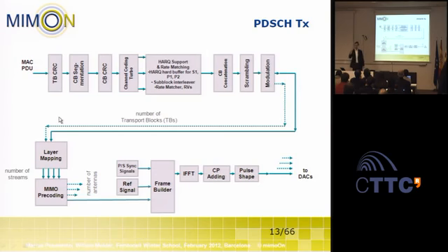So these up to two transport blocks can now enter the layer mapper, and in the layer mapper we adjust the number of streams that we have for MIMO transmission. If we have, let's say, a 4x4 MIMO system, we can use up to 4 streams that we simultaneously transmit from our antennas. This is achieved here in the layer mapper, where these 2 code blocks are further multiplexed into 4 streams. The streams in LTE are called layers. So we now have 4 layers arriving at the MIMO processor.